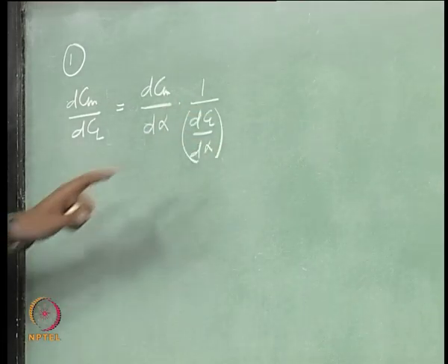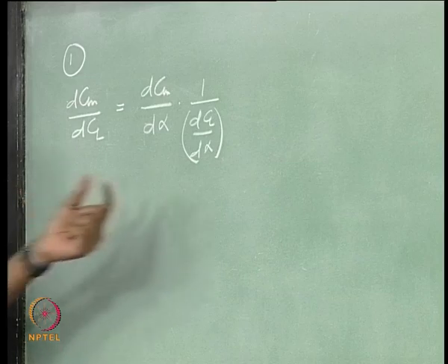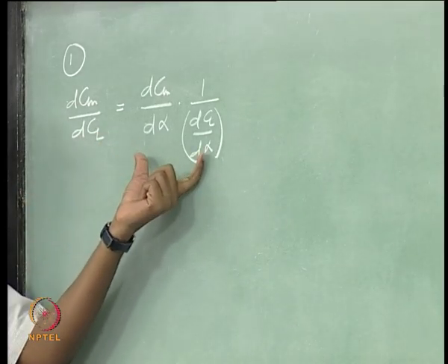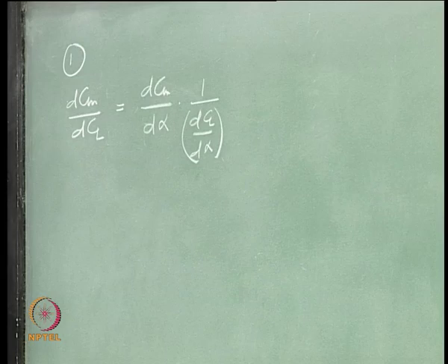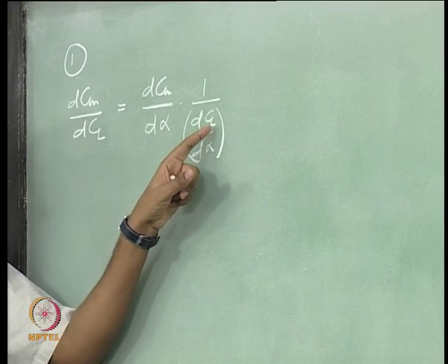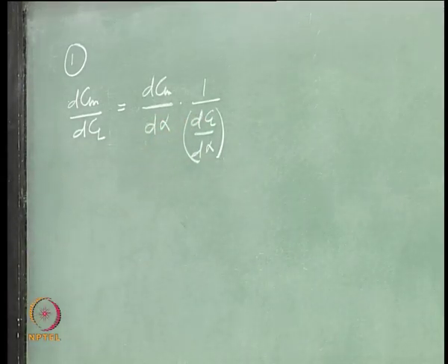Right. CL alpha is going to be positive for any airfoil you choose, negatively cambered, positively cambered or symmetric. So, this is not going to have any effect on the stability because it is a positive quantity, right. When you do this, you normally take this CL as the CL of the wing, right, because that is dominant, right.